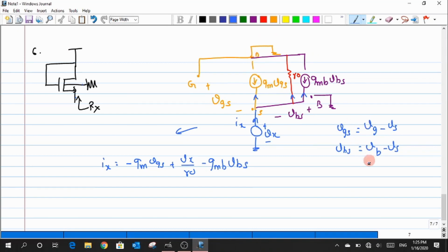So I have this equal to 0, and the Vs is actually connected to a positive potential Vx. So I substitute this for my Vgs, and what I have is minus Vx. The same principle could be applied for Vbs, and I would end up with the same result. So both my Vgs and Vbs have the same relation with respect to my Vx.